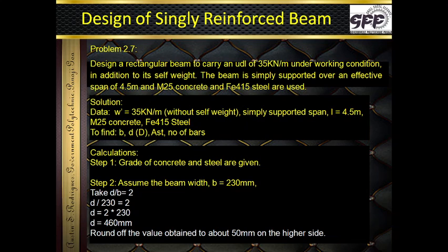Now when do we get a condition like this? Say a designer is actually designing a beam. He has already decided that the type of concrete is going to be M25. Maybe he has also designed some of the items. So M25 concrete and Fe415 steel is already decided. He has already calculated the effective span, and he has told us the effective span is this much. That parameter has been given, so that parameter cannot change. So having been given this, they want us to design.